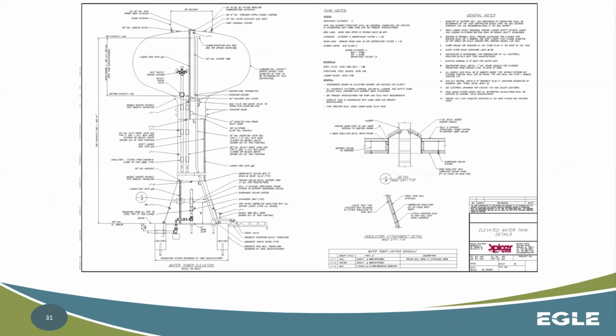Okay, this is just an example of a plan sheet here. You have an elevated storage tank that's being designed. You have this elevated inlet nozzle here, so it's going to be spraying out of these three different portions at a higher point in the storage tank. But this is not always the normal. Sometimes it's just an inlet and an outlet, just a single point coming in and out. This point here, if you can see, is the outlet.